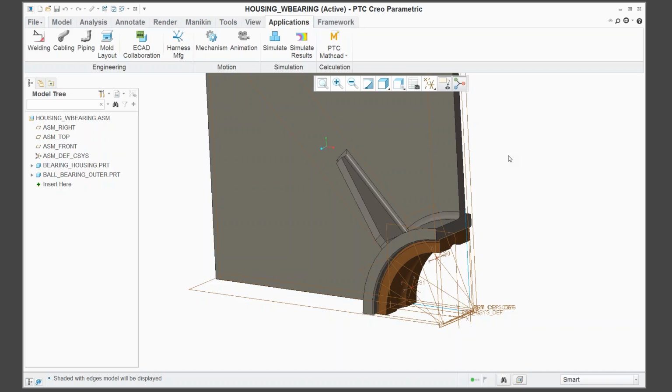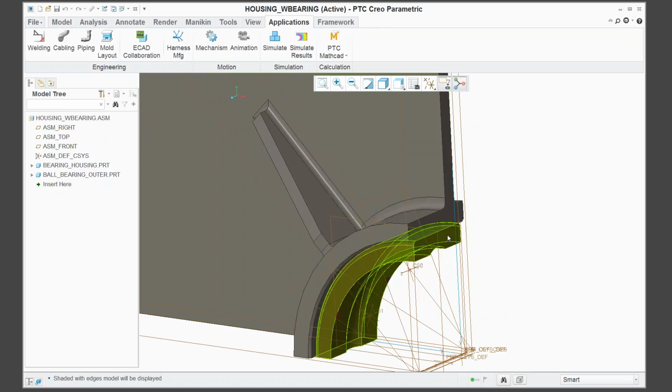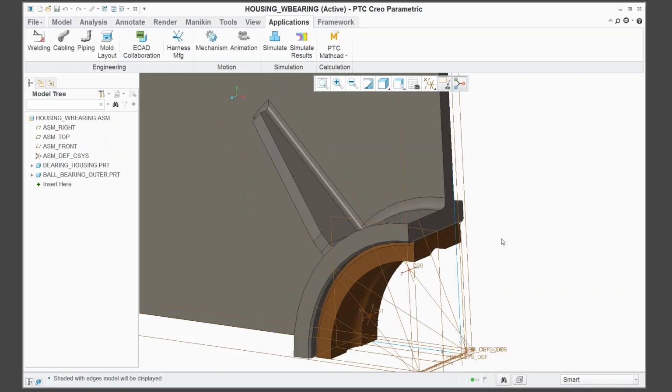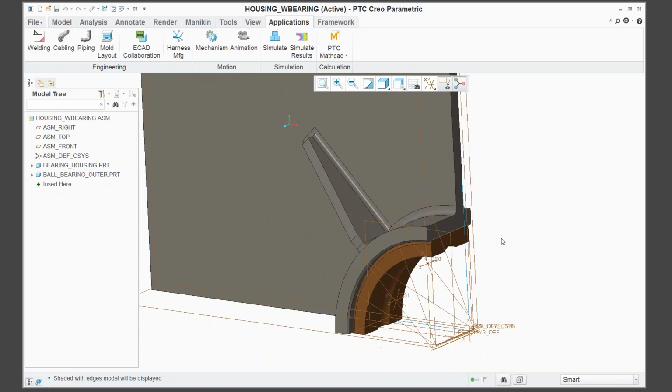What's a little interesting here is that this is a press fit problem. So this bearing is actually larger than the housing. The bearing, by the way, I think is about 1.6 inches in diameter, and it interferes with the housing by 1/1000th of an inch, which would be like a 1/2,000th per side, which might be a reasonable fit for a bearing. So what we're trying to figure out is what's happening to the housing and what is happening to the bearing race. And the housing you might think would be of more interest, but it turns out that the results actually show some interesting things with the bearing as well.